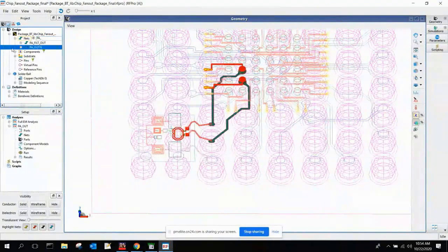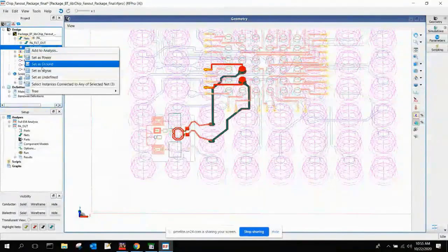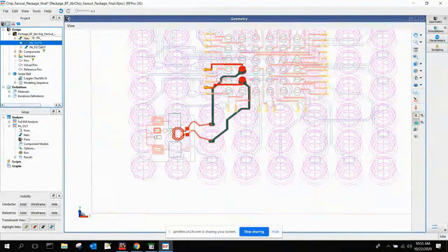These two are connected through this other technology through a balun. So these are two power amplifier nodes, but they actually create a single net. It's tracing the connectivity from the output of this through the bond wire, through the pad, through this balun on a filter technology, back out and to the other side. So I can take this net and make it a signal net. The signal net specifies 50 ohm termination as opposed to power and ground, which are low value terminations. And I'd move it over here.